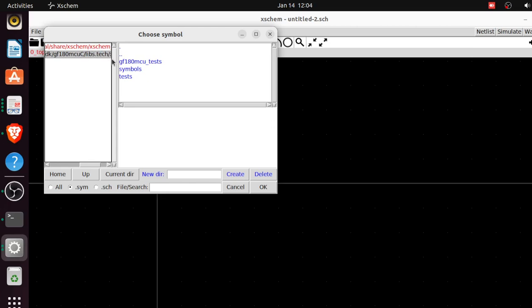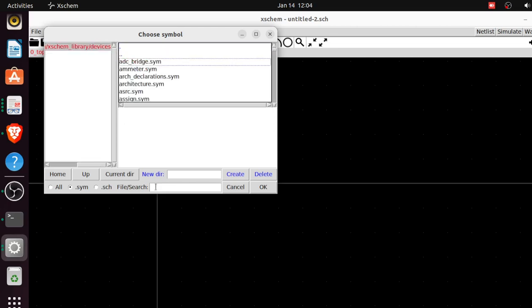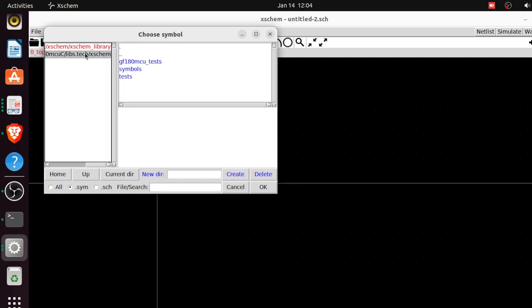So I want to pick a MOSFET, right? If you come here to the scheme library, you just search for NMOS. You're equally going to see NMOS here, but the thing is that we don't need the NMOS in the scheme library. That's not the NMOS we want. What we want is the NMOS from the PDK. That's what we need. So for yours it's going to be skywater.